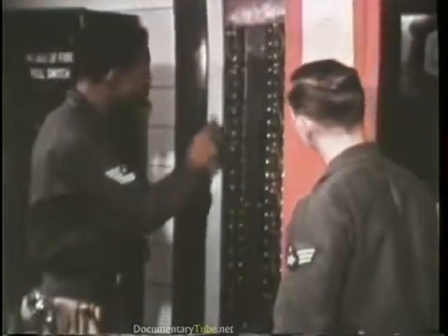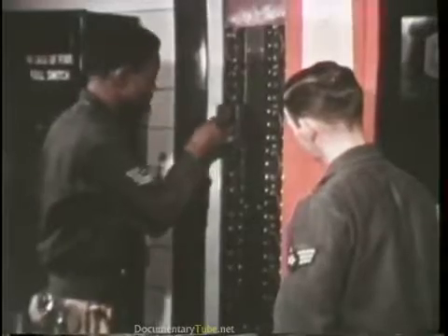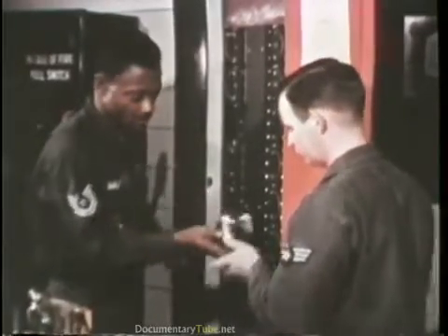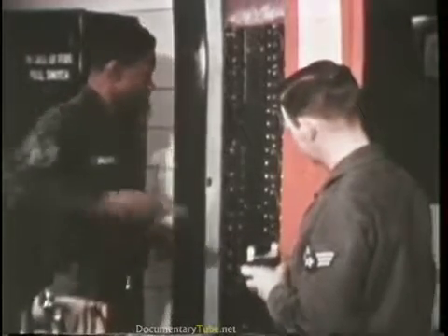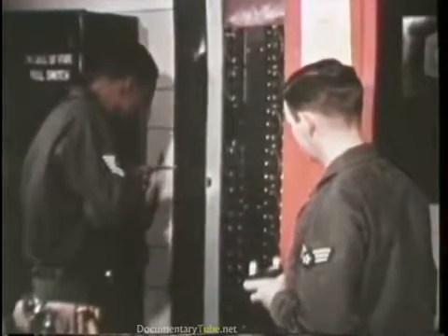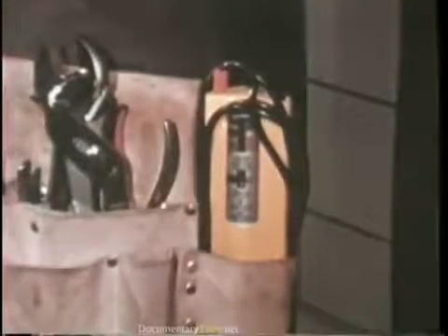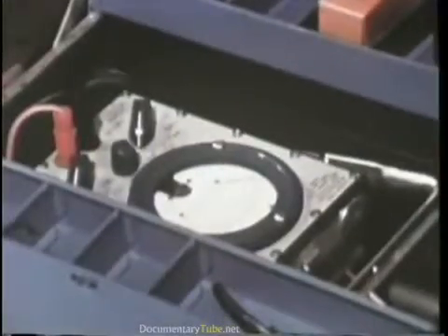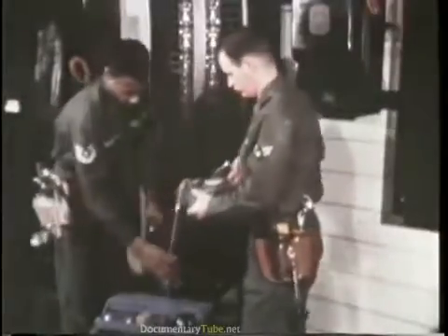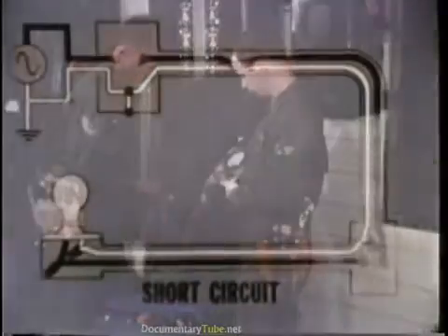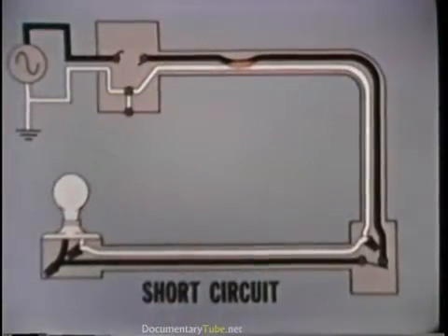In the field, electric circuits are generally installed in a manner that rules out a visual inspection of the wiring itself. However, to be able to correct any trouble, the electrician must be able to identify the type of malfunction that exists in the line. The correct tools and equipment will make this identification easier. The tools normally used for troubleshooting are a voltage tester and a multimeter or buzzer-type continuity tester. We will demonstrate the use of these tools to troubleshoot this familiar basic circuit.